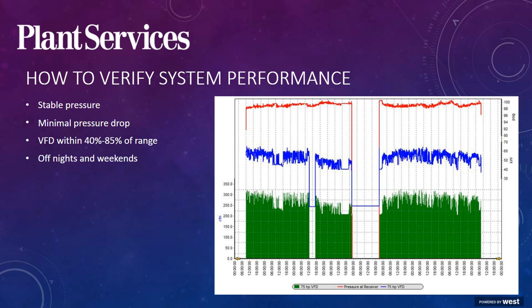And you can always incrementally change your system after adding a master and thereby seeing the effects of these incremental changes. So, let's say, you can see here, it's a little hard to see, but it's 100 pounds there at the top. Maybe we could do 98 pounds. Maybe we can do 95 pounds. Try to get closer to the set point. Obviously not trying to affect production, but get to a point where we're at the lowest possible energy consumption.